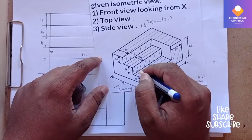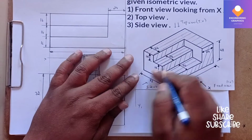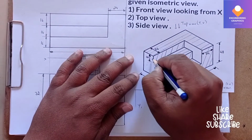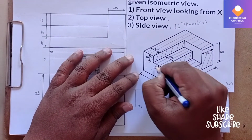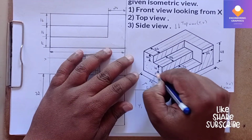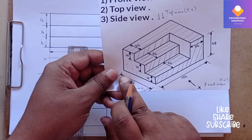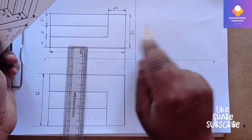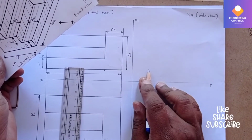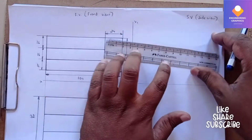You can see the side view we should construct. I will be shading that with the help of dots, the side view, so that we get a clear understanding of how to do that. You can see adjacent to the front view we have the side view. I'll be drawing the projection lines here.